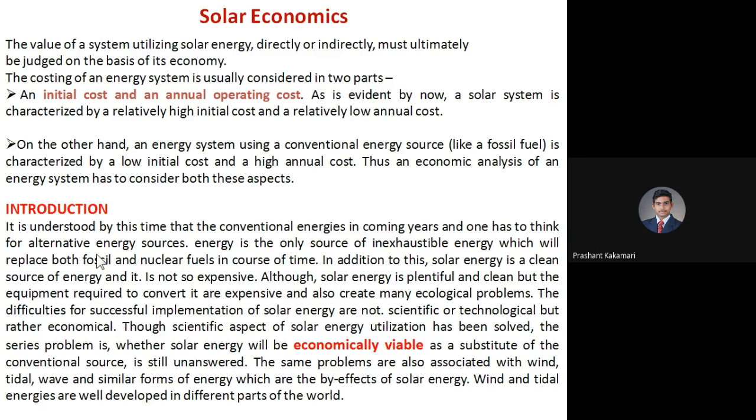Because if you see, apart from the PV system, for a given area the conventional thermal power plants are more efficient. In a given area, whatever megawatt or gigawatt power is generated by the normal conventional power plants is very high compared to these PV systems, which directly convert to electricity without any moving parts. But still, we have to compromise on the land or area required and the initial high costs. So here we need to talk about economic viability also, whether it's viable or not. Apart from this, you can also think about wind, tidal, wave, or ocean, or any other type of energy systems in a similar case.